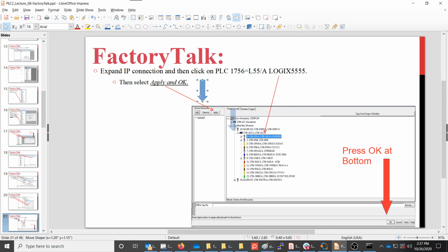All right, and what that basically does is tie this Lecture 7 name to this particular PLC. One thing with these HMIs, you could have one HMI program that's actually going to interface with multiple PLCs. And so what we're doing here is we're creating names. So this name really probably should include which PLC you're actually communicating with as part of the name, instead of just saying something arbitrary like Lecture 7, whatever that is.